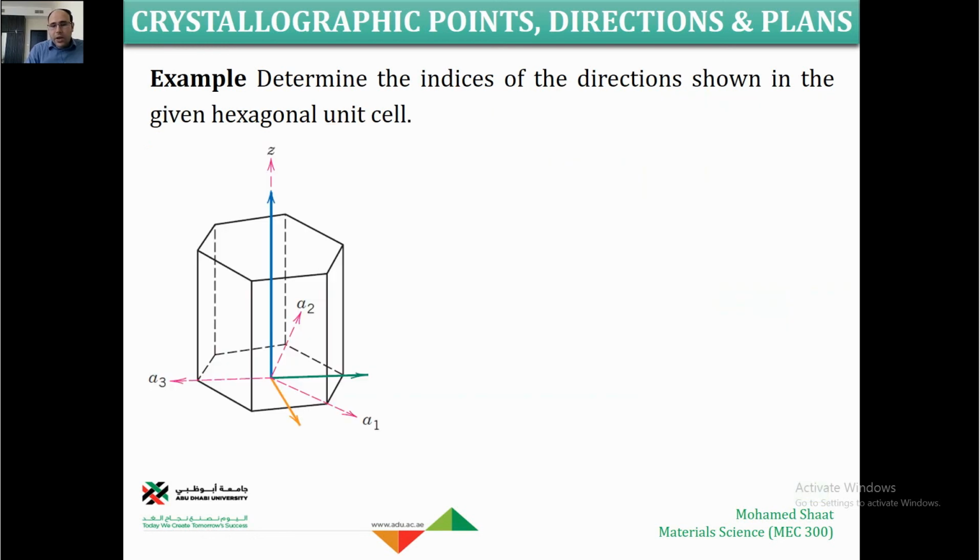Make sense? Another example here, how we can define this crystallographic direction for this hexagonal crystal. Let us start with the simplest one, which is this one. This is very simple. If you start from here, how long should you move parallel to A1 and A2? Forget about A3. You need to define first U prime. So let us give names: this is vector A and this is vector B and this is vector C. So, direction A, direction B. Let us start with direction A.